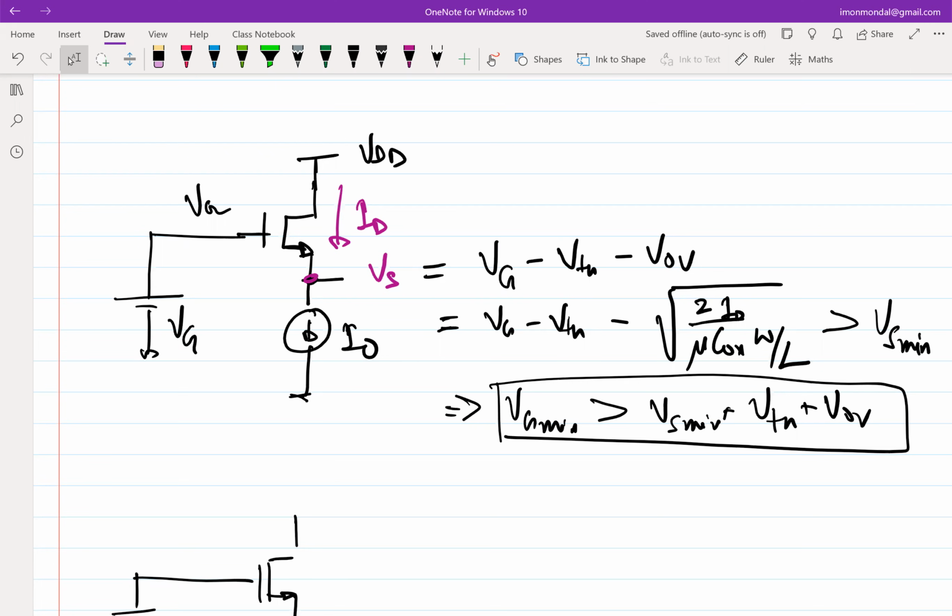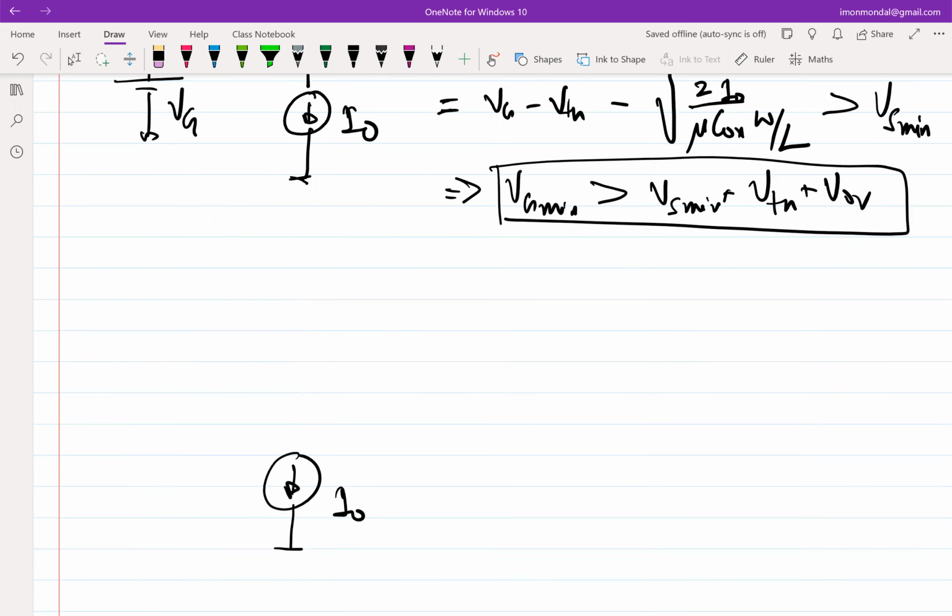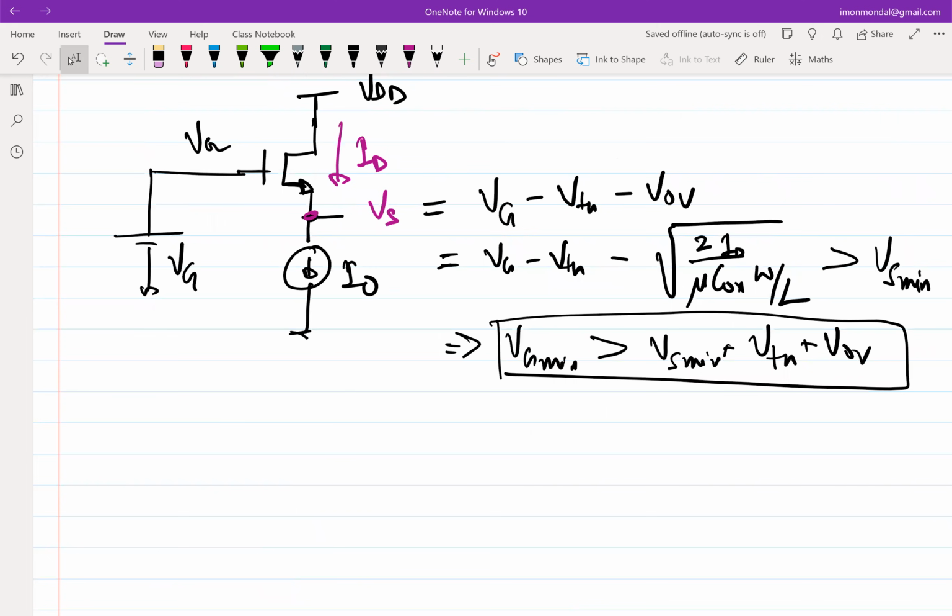Exactly, right? Since he raised the point, let me spend a couple of minutes on this. His point was that it seems we didn't have to do anything, the circuit biased itself. Why did it magically bias itself? Because VS goes in the direction we want, ensuring that ID is equal to I naught. Which means there is a negative feedback built into your MOSFET. From whatever we have learned till now, can we make sense of this negative feedback and quantify its level?